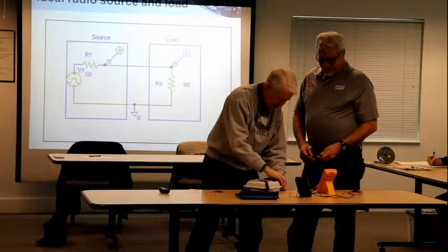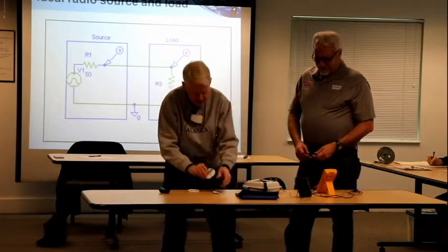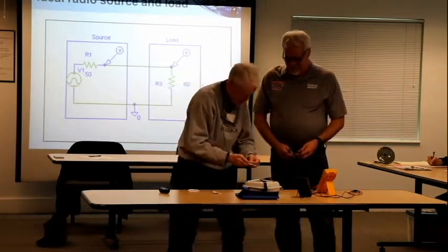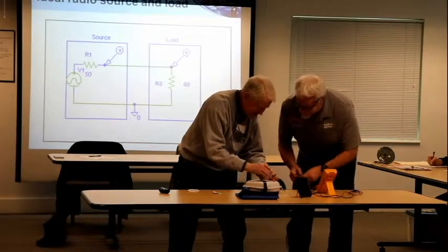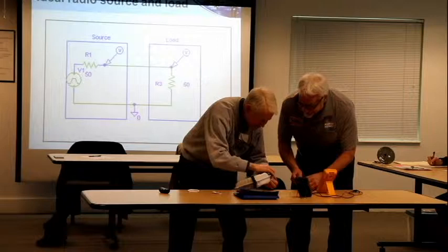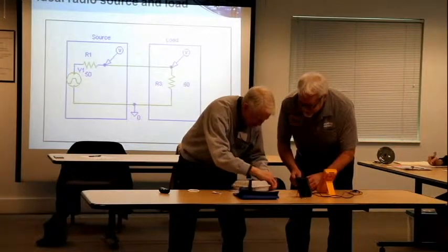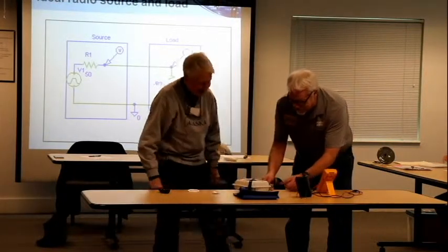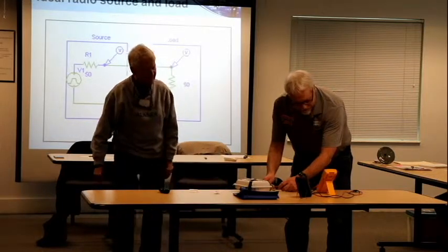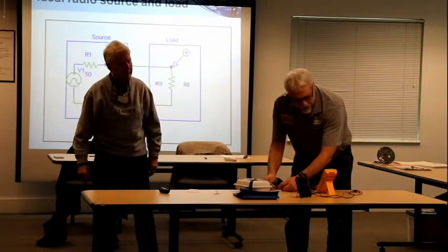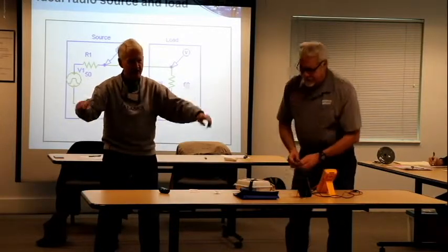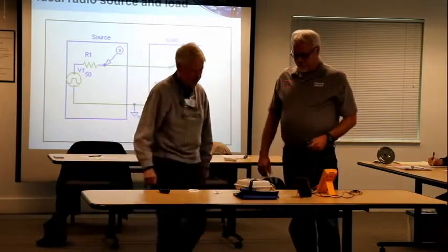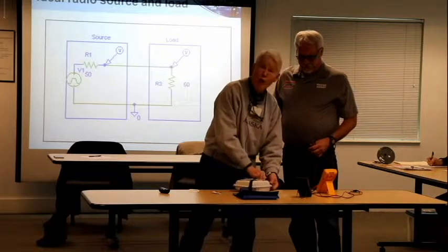We're going to do this two more times. Anybody needs to take a snooze, feel free to do that right now. We're going to try it with two more resistances. This is with the medium, 1,000 ohms. I tried this with a radio antenna. It wasn't as easy to do. But all right, in this particular one here, we got 4.7 volts. Write that down, 4.73 volts. 4.73 volts for a 1,000 ohm load.